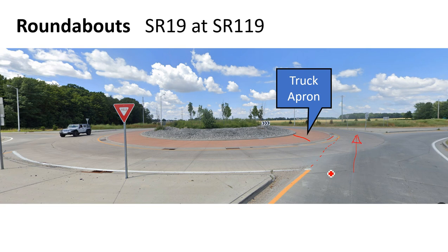And this roundabout's not that old, but you can see here was the shark's teeth, and they've already worn off. So those pavement markings don't last very long, right? Typically you got to restripe every 2 years at a minimum, and if it's paint, probably every year. Through that. And this is a pretty high traffic one, a lot of truck traffic, so these markings get rubbed off a lot quicker through that.